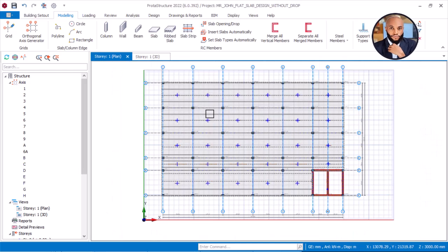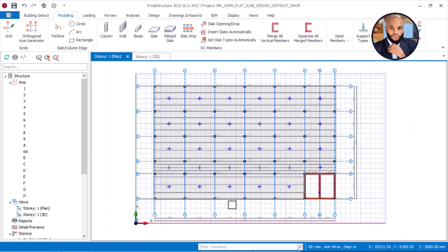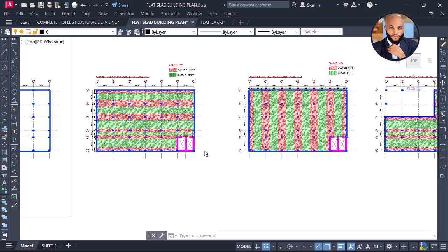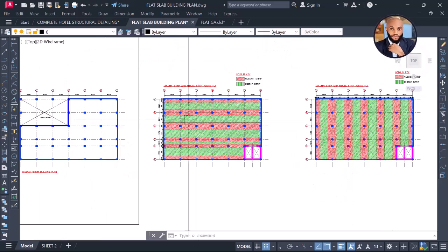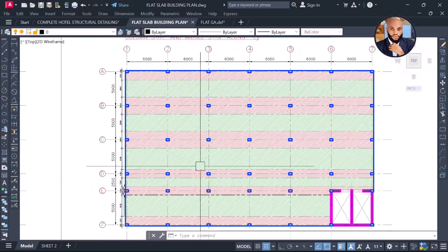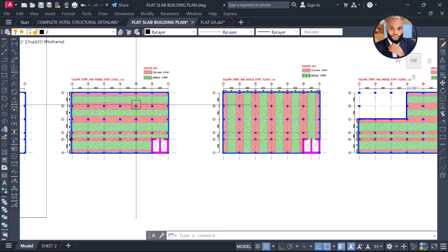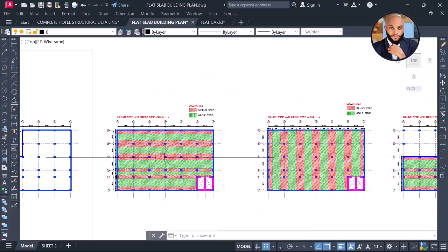Like I said again, if you want to collapse a structure when it comes to flat slab, do not calculate your middle strip and column strip. That structure will collapse because there must be a punching. But once you are sure you don't want to tag your name as the engineer that collapsed a structure due to structural failure and miscalculation or misdesign, then you have to do this perfectly. And by doing this, you can see that we spent part 1 and part 2, over 1 hour, just to teach you this. So make sure you do this perfectly before you can do your design.